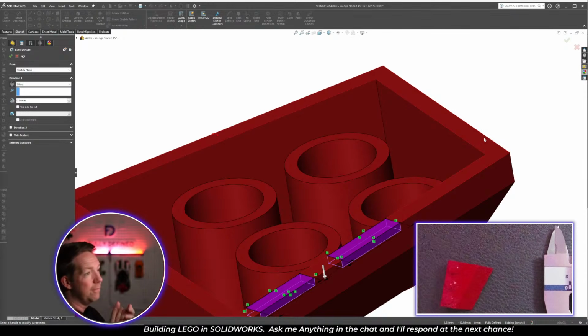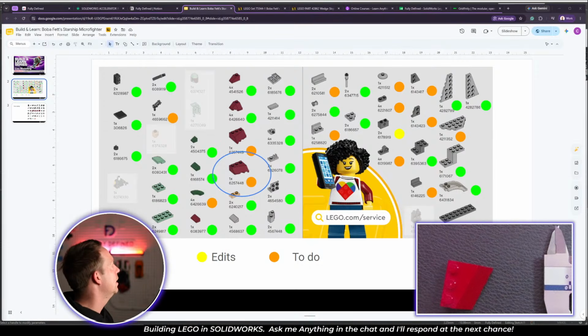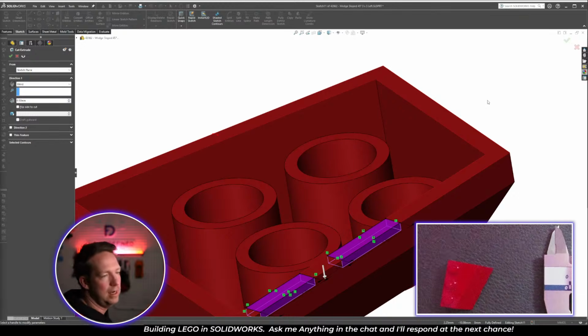And I have some examples of that in different videos on the YouTube channel. In CAD, it's usually called a master model, or a skeleton, depending on how different people use them. Master model is terminology I use regularly, because I'll have a master model that is driving a lot of detail and a lot of the geometry, a lot of the parts, and then I'll split those parts out into child parts afterwards.